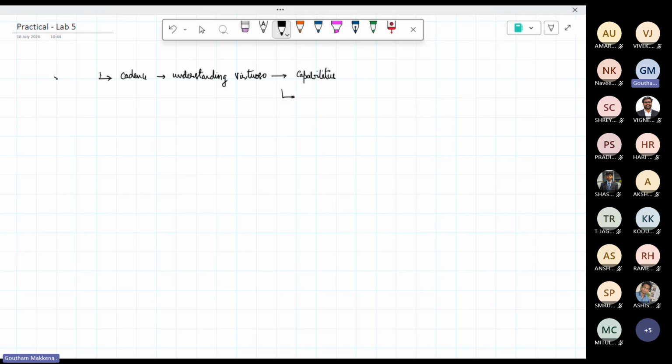So fundamentally, what are those capabilities that were useful to us? It gives us access to small signal parameters. You know that big drop down from which we select those small signal parameters, right? GM, GDS, CGS, CL, all those things. So all the access to the small signal parameters.